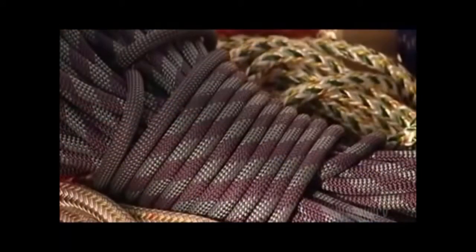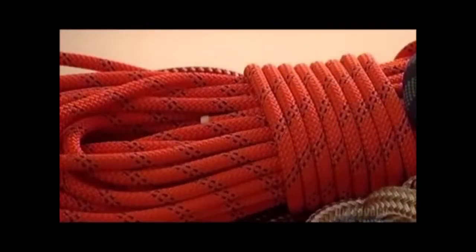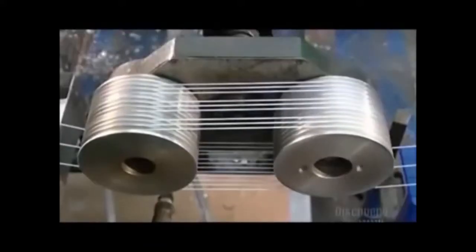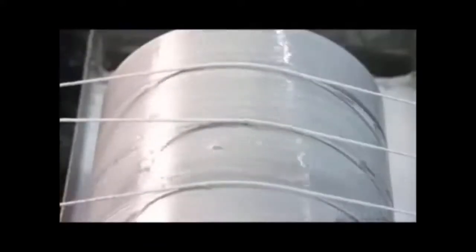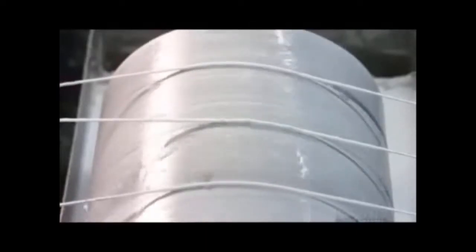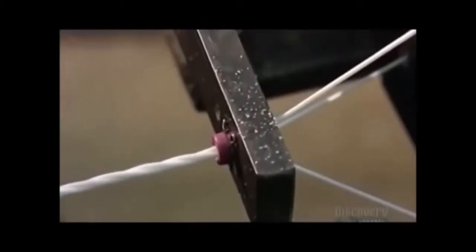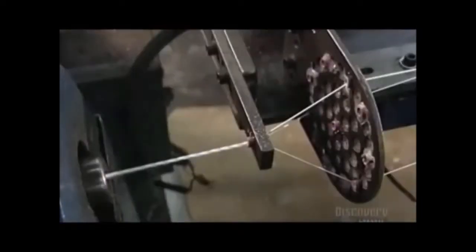These ropes are made from thousands of nylon fibers that are finer than human hair, but stronger. To make rope, yarns wind around aluminum cylinders, pulled by a turning spool down the line. Then, 3 at a time, the yarns roll over another spool that applies a protective coating of urethane. Then they funnel through a distribution plate that holds them evenly apart. This ensures they're at an even tension as a rocking spool twists them into one larger yarn.